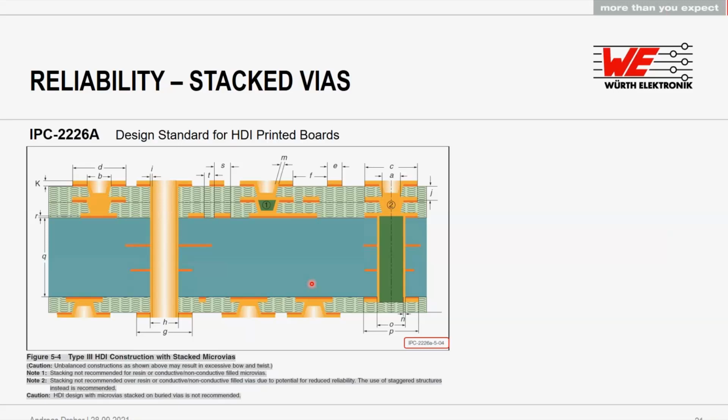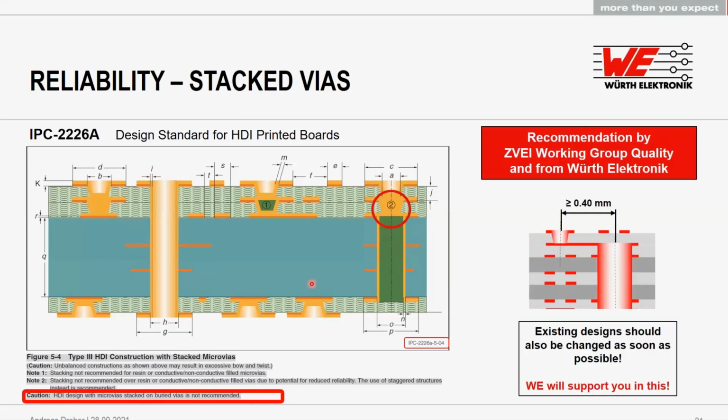Not everything in the real world which is shiny is gold. So it is also with stack ups on different microvias. There are some combinations which are not really recommended. A few years ago, the IPC announced that directly stacked microvias on top of a buried via is not recommended. This is also supported by some investigations by Würth Elektronik or the ZVEI working group of quality.